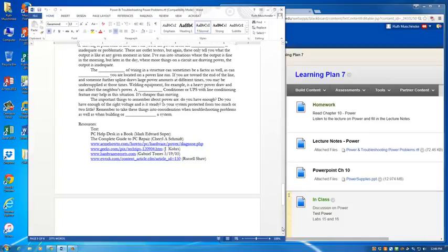Electric welding equipment, for example, is a heavy power draw and can affect the neighbor's power. A line conditioner or a UPS with line conditioning feature may help in this situation. It's going to be cheaper than moving.